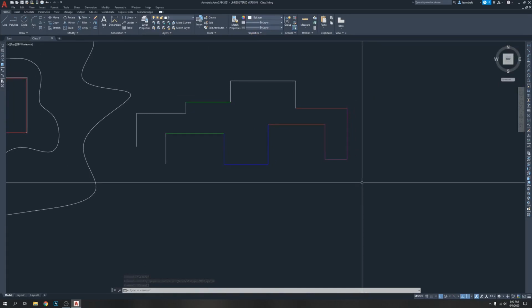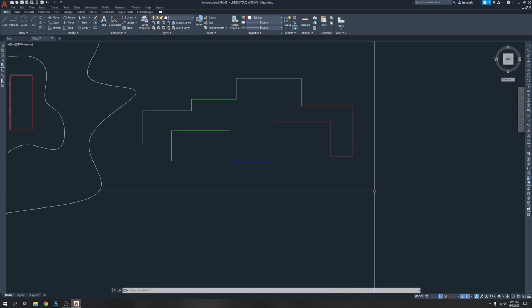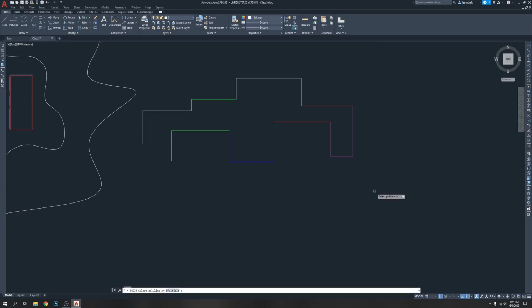Now you want to make it PolyEdit. PolyEdit means those lines you can put together. There are two ways you can do it: PolyEdit, and the other is called join. Joining has some other things with it. PolyEdit has some other power. So we are doing PolyEdit. So let's put the command PE, which is PolyEdit, enter.